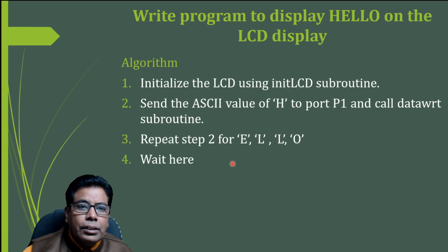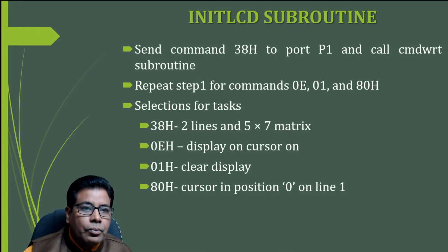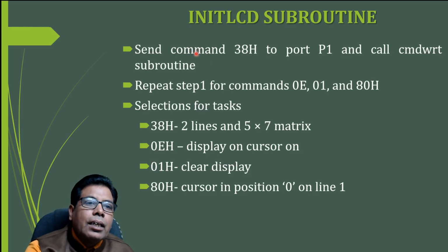So first let us see the INIT LCD subroutine, that is for initializing the LCD. So first part here, send the command 38 to port 1.